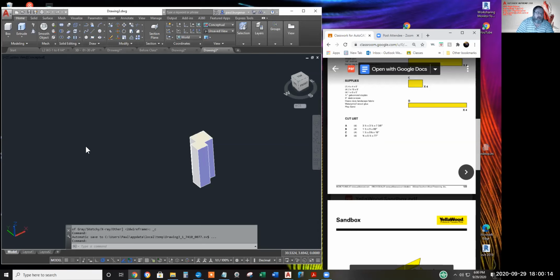Now, depending on how we make the board, we may end up having to rotate it 3D to get it upright. If we create it flat on the floor, we might have to rotate it on an edge. If we plan ahead with our box command, we can avoid that 3D rotate step.